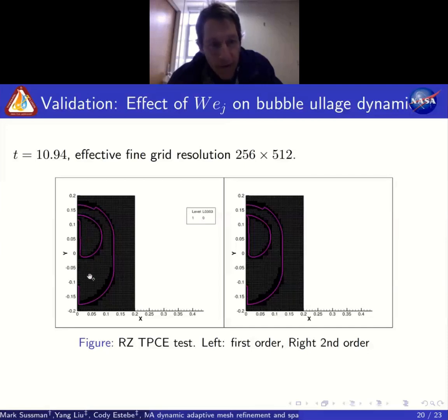In this case, on the coarse mesh, the flow is not as accurate. Especially here where one has the jet, we don't adapt the grid. And if we do a low order method, the jet is diffused and it delays pinch off.